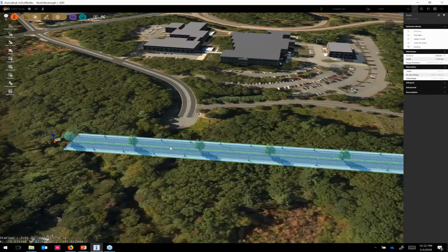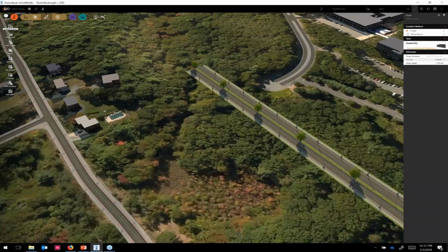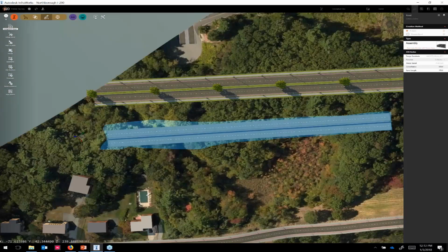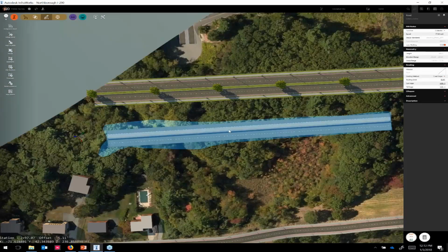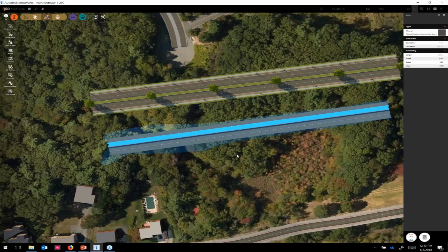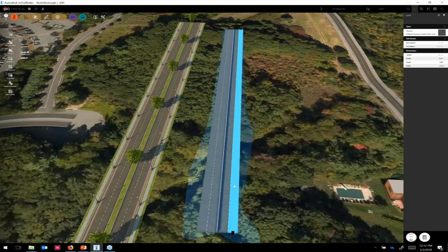However, if I created a component road, you have a lot more fine control over the elements. The design here is more focused on longitudinal design, so you will have control over being able to select individual aspects of the road. In this case, I'm selecting a lane, or I could select a Jersey barrier and define the attributes on that individual component.